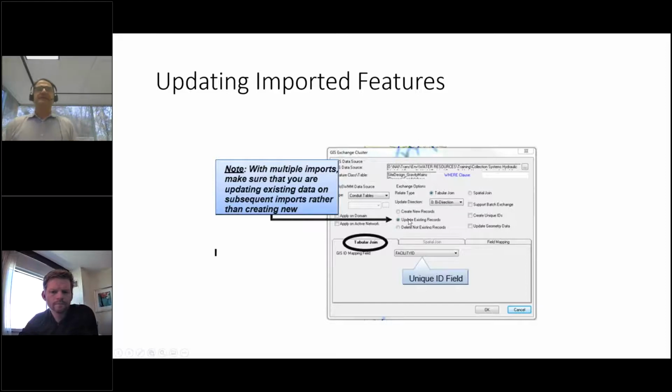Because in this case, you might have corrected all the diameters which were in text, for example, 8-inch whatever, and imported them, and now you have updated some inverts in the model, because after you imported, you look at drawings and you fix those inverts. You don't want to reset those to what was in the GIS originally.